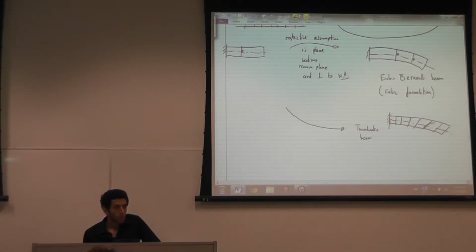So whenever you're using a beam, you need to realize that you're assuming plane sections remain plane, and hence you're able to remove this whole beam and just replace it with the neutral axis of the beam. Because knowing the location of the neutral axis, because of that perpendicular plane, you know the location of everything else.